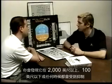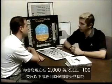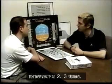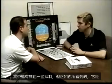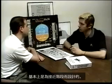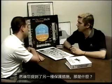It's really something that's available only during the approach phase. If you read through the long laundry list of items for when this is inhibited, you'll see that it's inhibited above 2,000 feet, below 100 feet, or any time our flaps are not 2, 3, or full. There are several other inhibitions in there, but as you can see, it's basically designed for the approach phase. And then you mentioned another protection, which would be what?